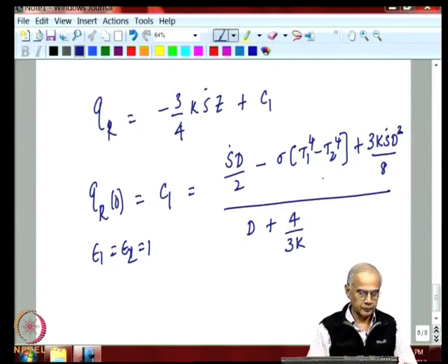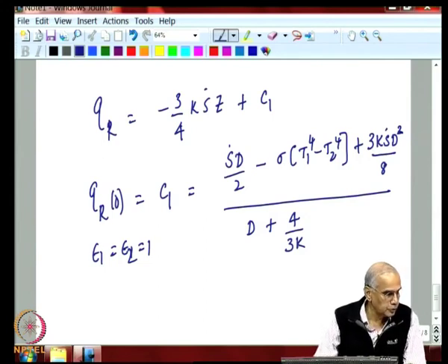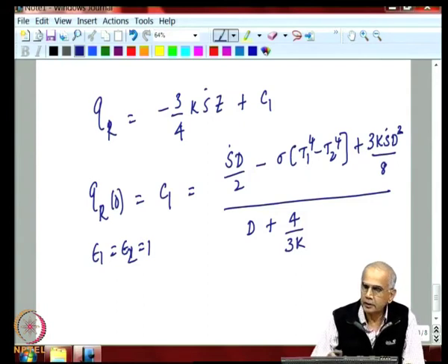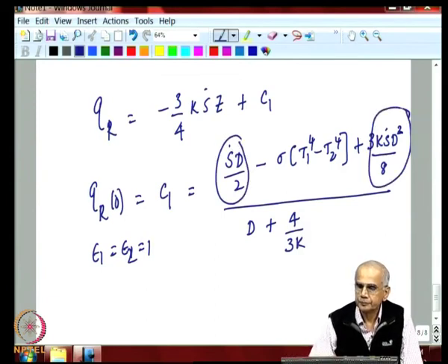In the previous problem, the heat source term was not there, so its role was not clearly highlighted. But in this problem you can see clearly that the internal heat source term can become quite important and completely alter even the sign of the flux if it so happens.